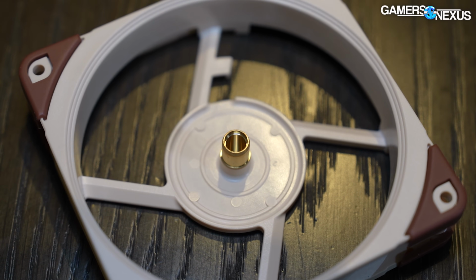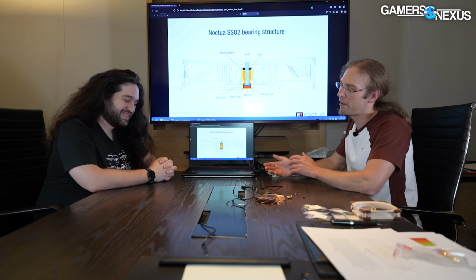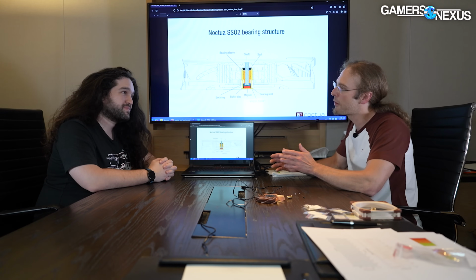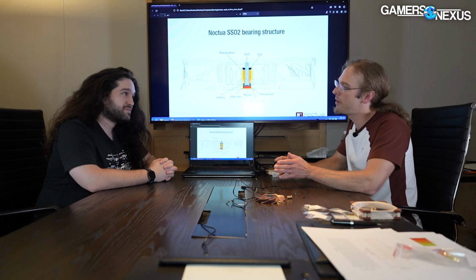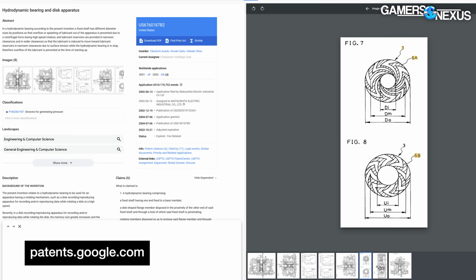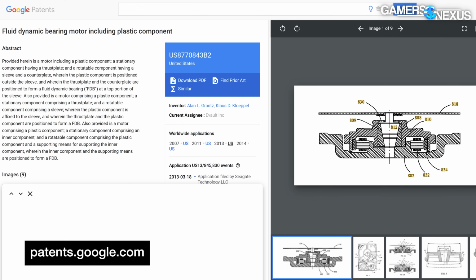But even then, I think it's important to understand where this structure comes from. The basic concept of adding grooves to enhance lubricant circulation is very old. This dates back more than 100 years, to 19th century early tribology experiments by Reynolds and so forth. So this is very old. And then we need to look back into the 80s and 90s, when a lot of the so-called FDB patents were filed by companies like Matsushita. But the background of these patents was hard disk drives.